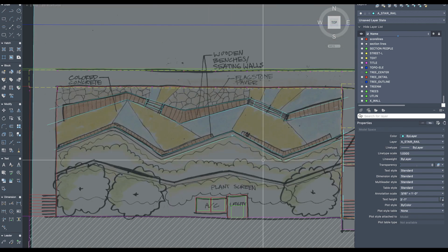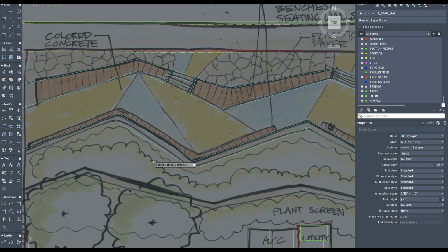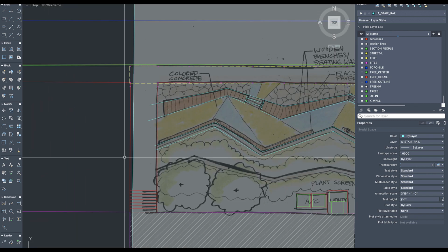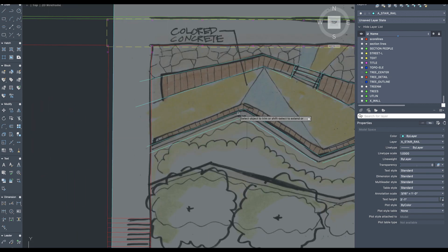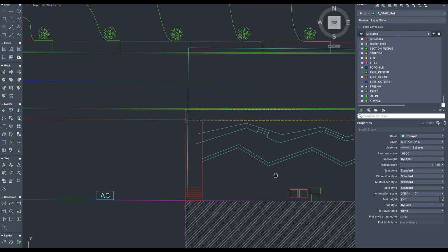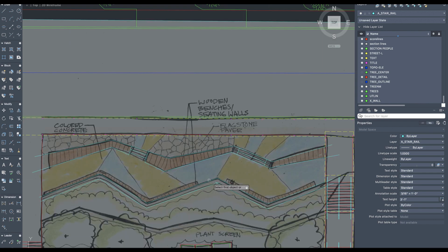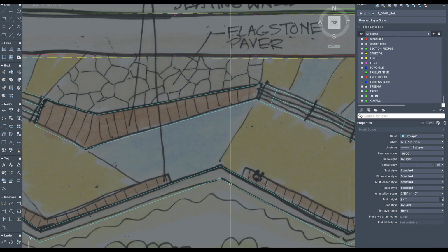Now, you can notice that there's a little bit of overlap here. There are gaps here. That's going to happen right in this area. Now, there's a couple ways to get around that. One is just, hey, let's get the trim tool out. Let's start to trim. Let's extend in a few places. We'll extend that one, extend there, and trim. Another method would be to do a fillet tool, and we set our radius, so F space, R space, and we set the radius to 0, and we can attach those there, and it will even trim these right here.